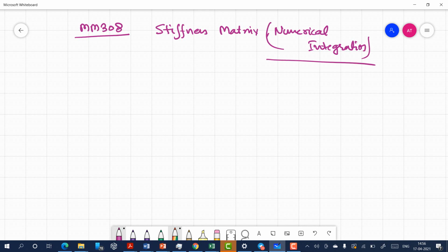You should practice calculating the shape functions using Lagrangian formulation for different types of element. You should take that as an assignment, or it should also be discussed in the tutorials. For instance, we have done it for this simple element for which we explained the concept.